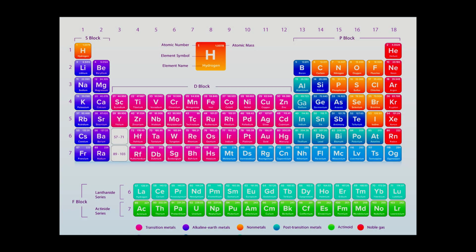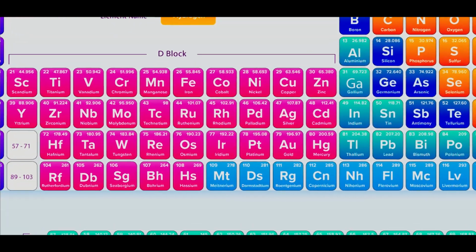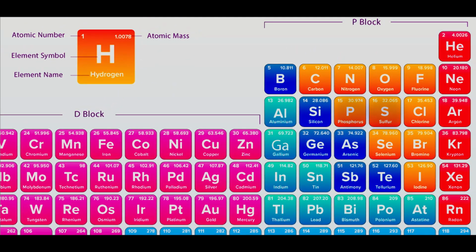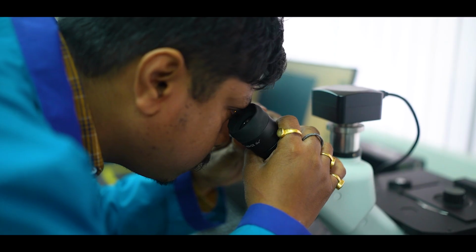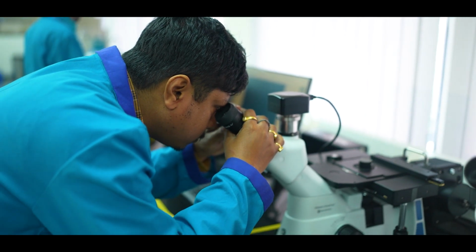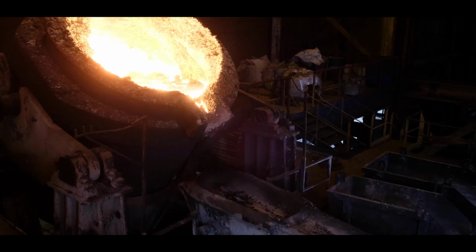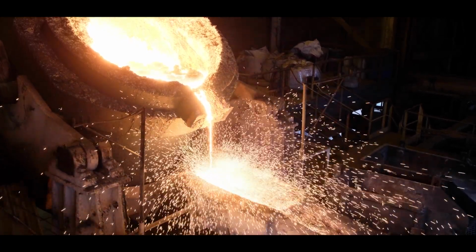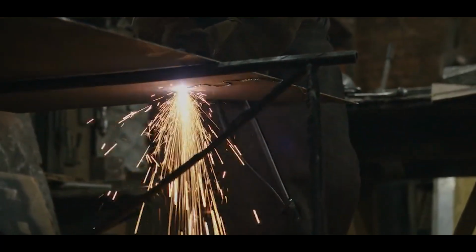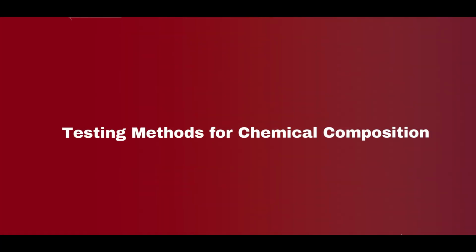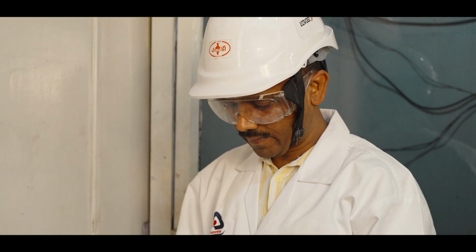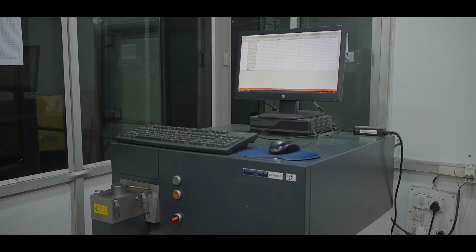The chemical composition of steel is crucial for its performance in hollow sections. Strict control over elements like sulfur and phosphorus help prevent brittleness, while elements like manganese enhance toughness and ductility. The addition of microalloying elements improves strength and grain structure, all while maintaining weldability. For welded sections, controlling nitrogen content is essential to avoid cracking during welding. The chemical composition of steel can be verified through ladle analysis.